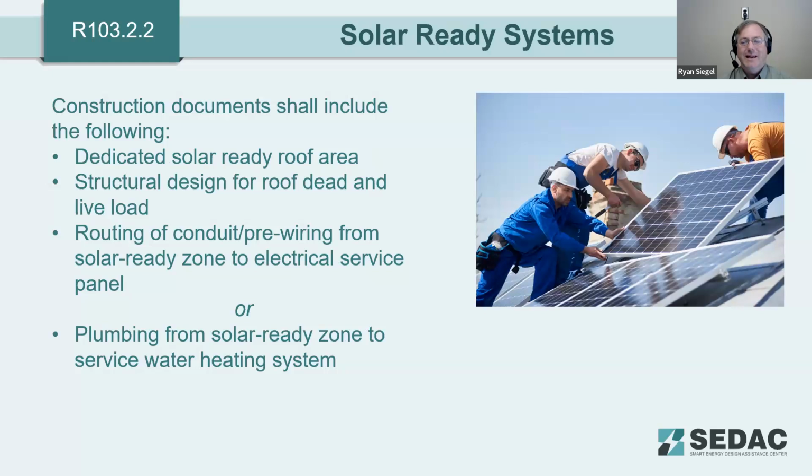We also have solar ready, recognizing that solar continues to get cheaper and more attractive over time. And so the construction documents calling out where the dedicated solar ready roof area is, incorporating any structural design for future solar installations, and then the routing of conduit and any pre-wiring to the electrical service.